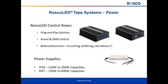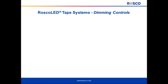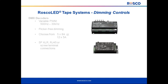For those that want to do more customization, or have a larger project where maybe the control boxes and kits aren't the ideal solution, we do offer a full range of discrete power supplies and dimming controls. We've got power supplies with different capacities rated for both indoor IP20 as well as outdoor IP67 applications. Our DMX decoders are somewhat unique in that they've got an adjustable pulse width modulation frequency. They can be adjusted from 500 hertz all the way up to 30,000 hertz.